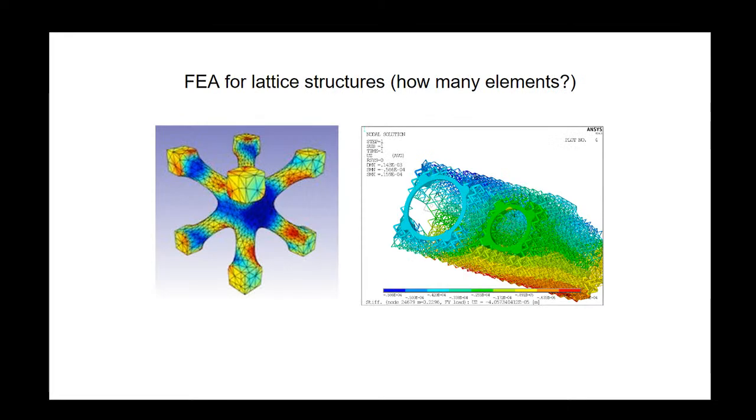So when it comes to simulating such a complex model like a lattice structure, we need to start simplifying it, make it simpler. Beam and shell elements are actually much better suited for simulating lattice structures because dividing a lattice into many smaller solid elements would take a lot of computing power. So imagine how many 3D elements it would take to mesh one beam of this lattice, and now multiply that by the number of beams. Since a lattice structure is typically made up of just interconnected beams and surfaces with usually a uniform cross-section, we can simplify the model into 1D and 2D elements. And then we can simulate a much more complex design with a lot less computation time.